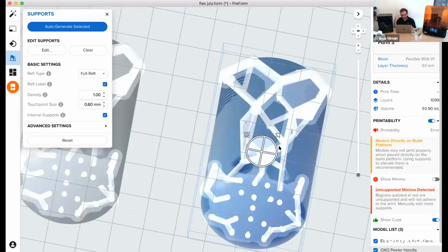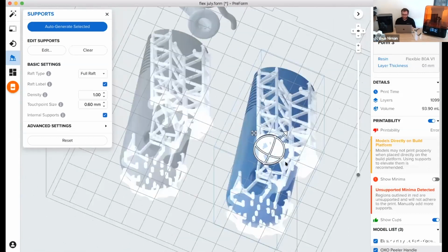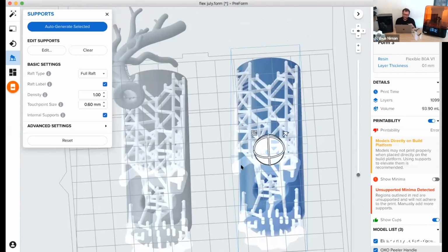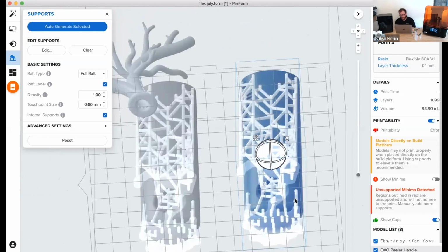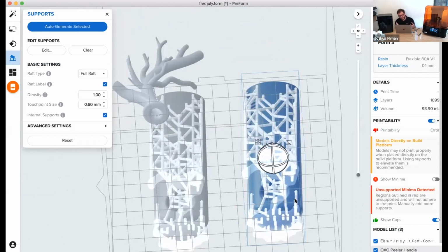And so in my head, I have a gut feeling of, okay, I'm going to need about this many supports. I don't mind placing them. I can place them pretty quick. For something huge and blocky, for something that I know is going to involve hundreds of supports because it's a 4-inch cube or something like that, I go auto and then I remove the ones I don't want.